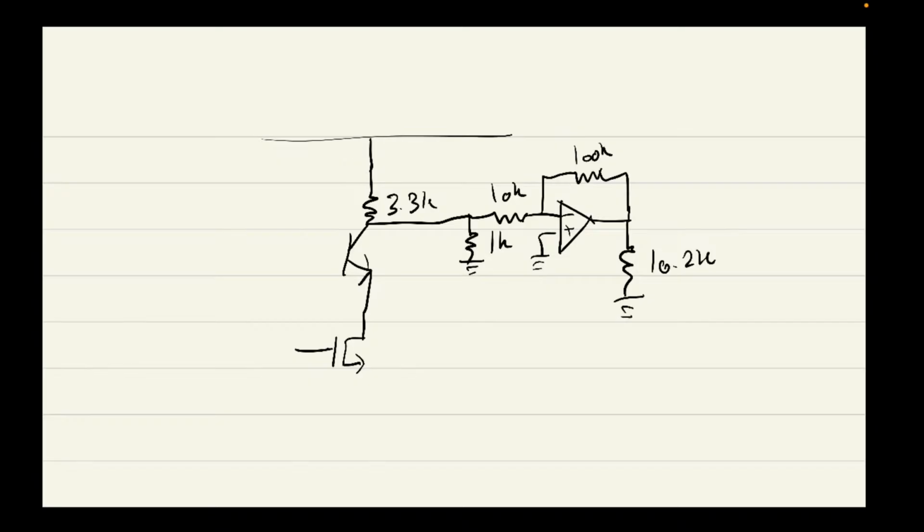Okay, so what we'll do over here, there's some working out that I want to skip in the interest of finishing the question, but I can essentially find the Thevenin equivalent of whatever's on this side and then replace it with that, so it's a bit simpler.